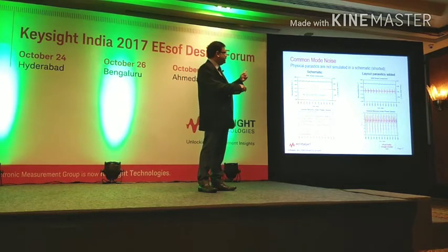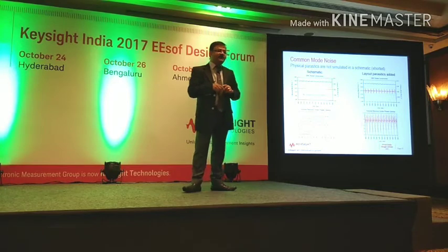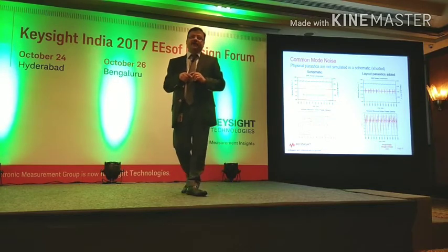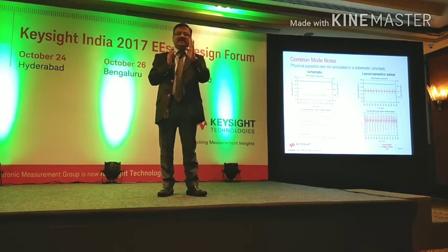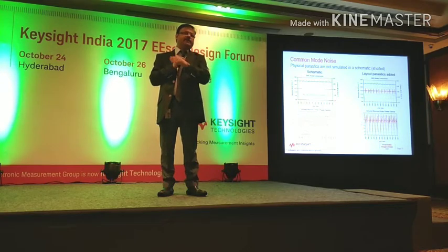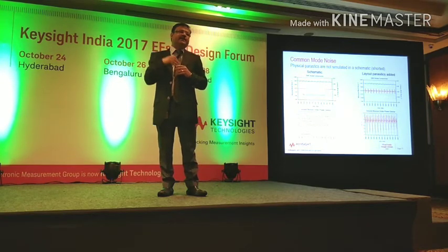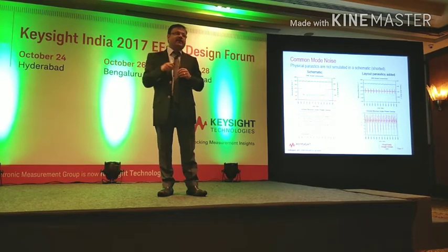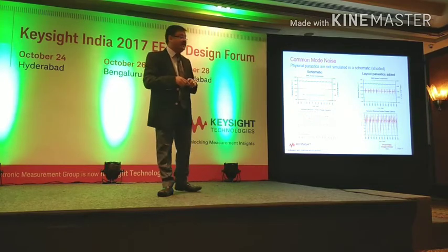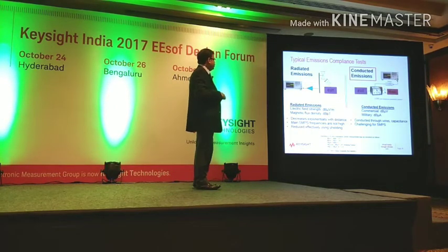Higher switching frequencies mean the layouts are becoming that much more important. With anything above, let's say, 100, 200 kilohertz of switching frequency, you cannot just close your eyes and draw the layout. Each and everything will matter. You'll see how. Let's quickly go through how typically you measure the compliance.